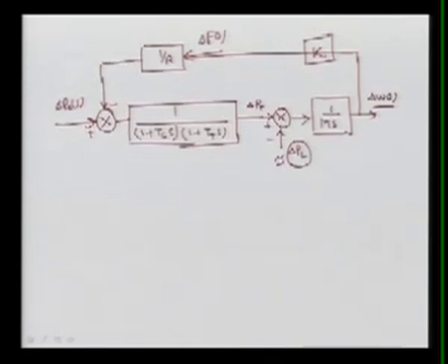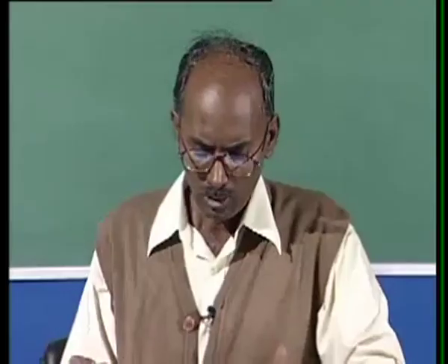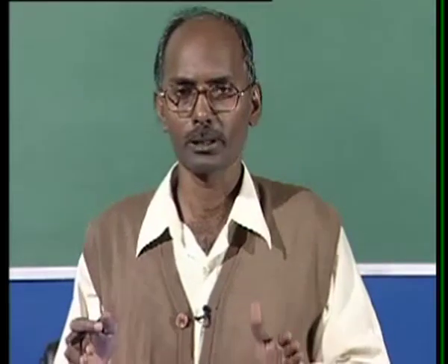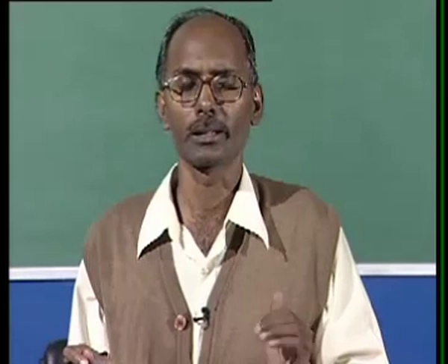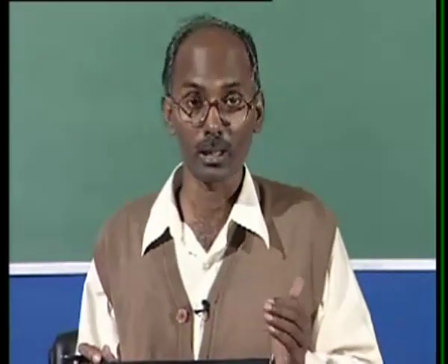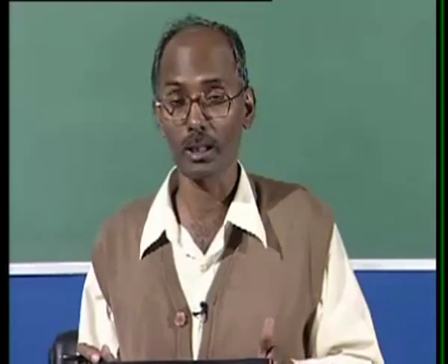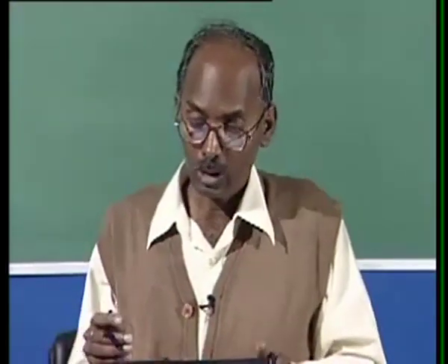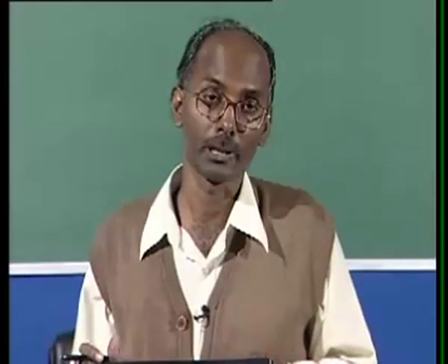So we will try to model this change in electrical power. Here it is the change in the load plus some other factor, and that modeling of load will give the system here. Now let us see, in the power system there is not only one generator, there are so many generators. They have different R characteristics, that is regulation constants. R will be different for the different generators. How will they share the load if they are operating in parallel?